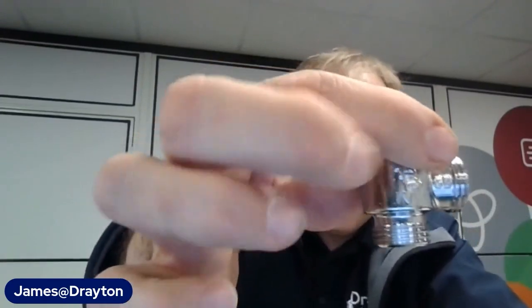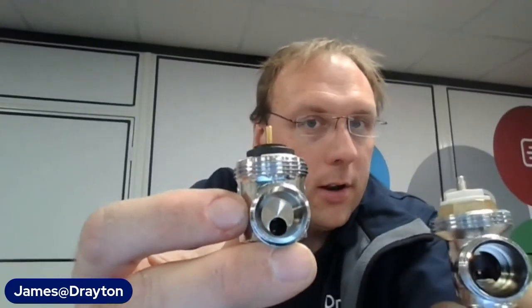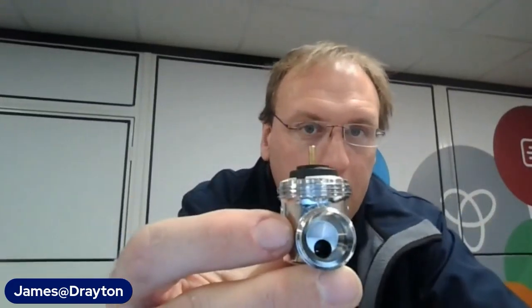So this comes with the RT414 and the TRV4, but when you look at a side by side, if you're using super low flow temperatures, you're probably better off with the 212 body if you need to get a lot of flow through the radiator, because the EB body comes with built-in resistance by just having that, I think it's something like a 6mm hole on the output. And when you look at the bottoms, the inputs are pretty much the same.